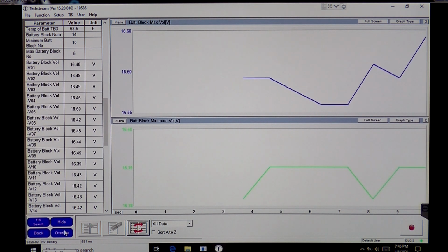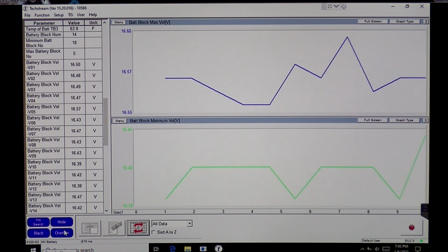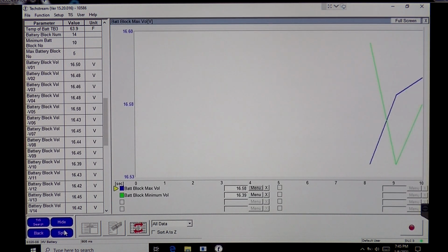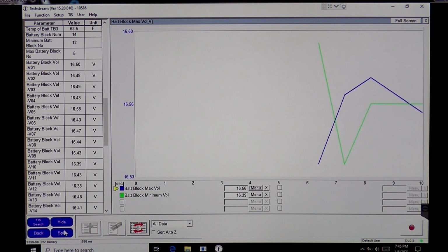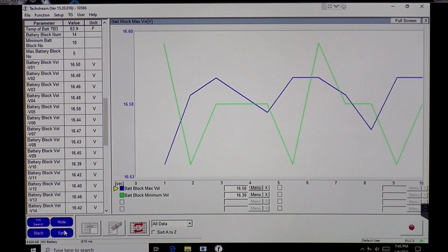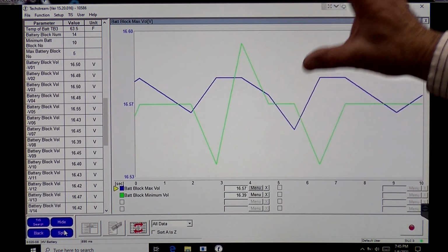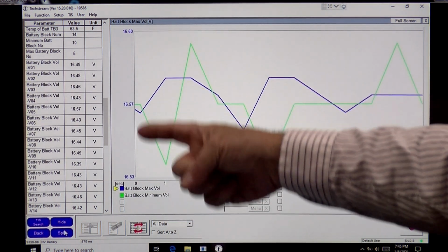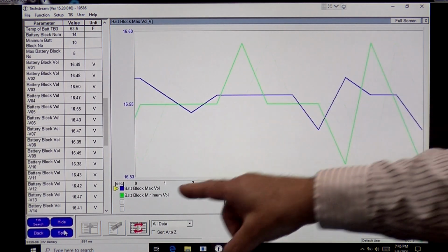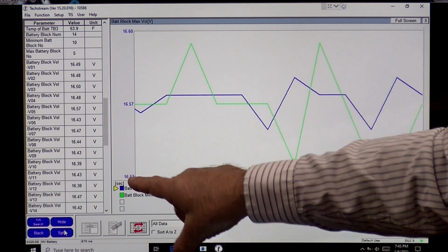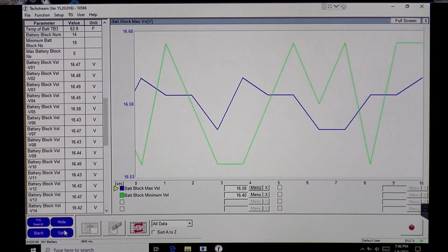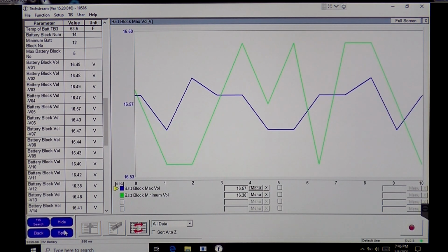So if we look at these two, we could see, by the way, even overlaying them, that the voltage does change somewhat because the car is on. And it's just graphing it out. But always when you graph, look at your scaling numbers. It's not really changing a lot. It looks like a huge change, doesn't it? You're only going from 1653 max to 1660. It's not a huge change. That's the whole scale. So you could graph out some neat stuff.